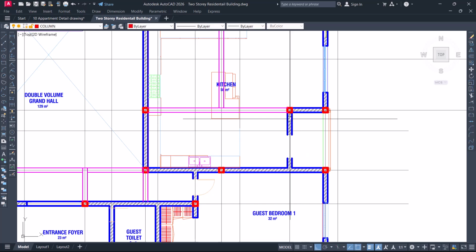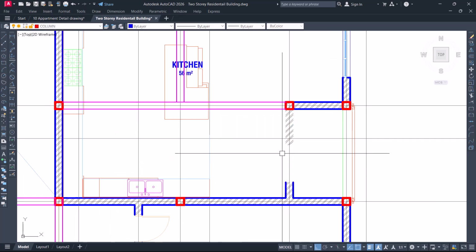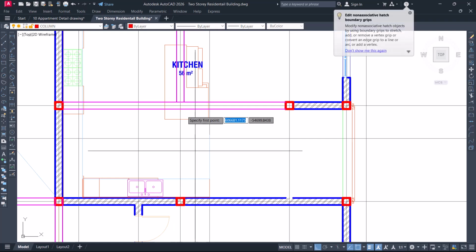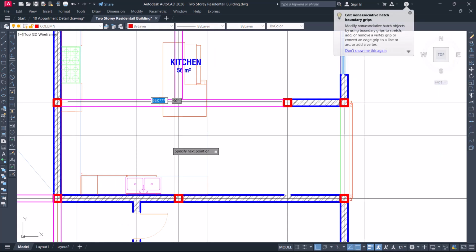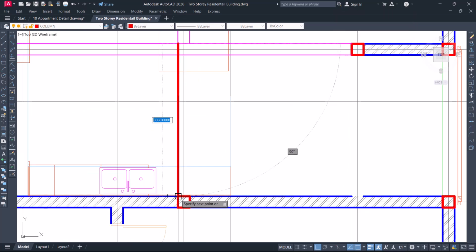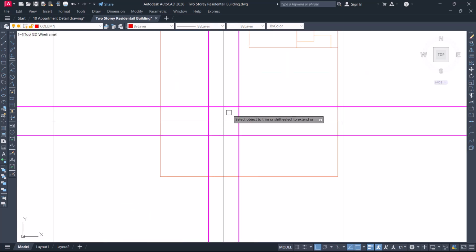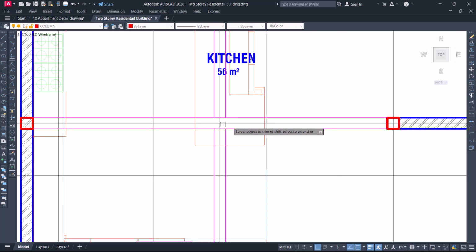Okay, remove these two as a beam. Okay, these two should go as a beam. That's fine. And I'll remove this. Then I'll have a beam crossing here. So I'll cross this like this, from here all the way down here, offset 225. Then I'll come here, have this like this. Then I'll have to trim off this beam because one of them will carry the other. So the shorter one becomes the primary beam. So this beam now is what is carrying these two beams.